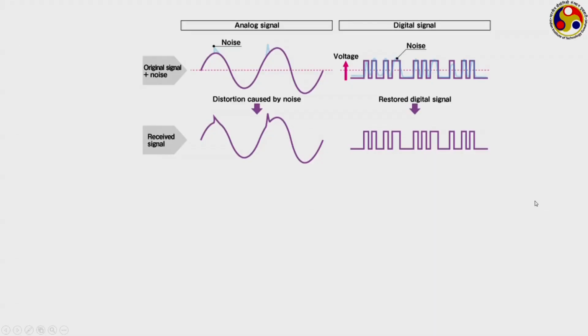This is one advantage for digital signal over analog. In the analog signal, you can see there is certain noise appearing, one here, another one here, and accordingly our signal has a distortion at this point and this point. But compare that with the digital signal. It also experiences a significant amount of noise, but as the data has been digitized, instead of dealing with a continuous representation like this, we have converted it to a set of numbers, so that hardly gets influenced by the surroundings, and we get exactly the correct representation on the output side.